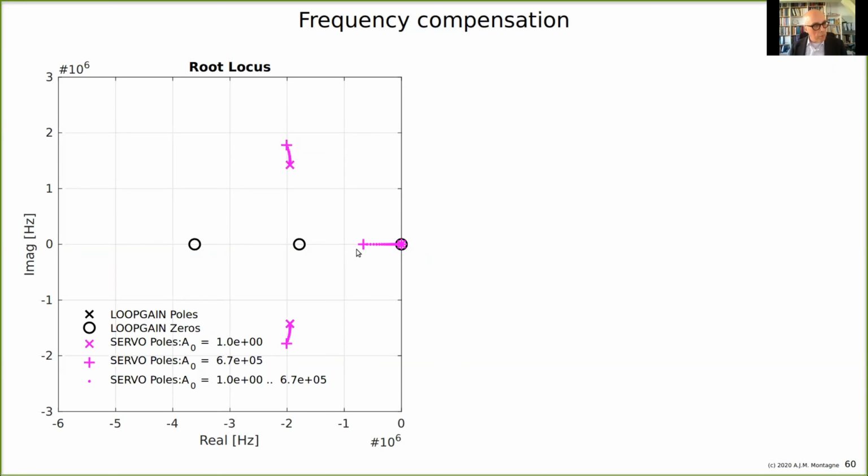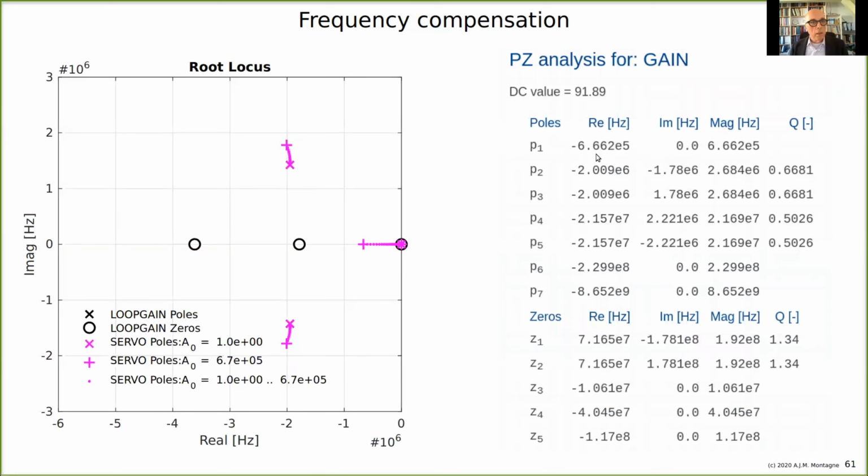So this is the dominant pole. So the bandwidth is limited to, well, maybe like 700 kilohertz or so. And then here at 1.5 megahertz, somewhere we have extra 2 complex poles, but they are almost in Butterworth, you see. So this looks pretty nice.